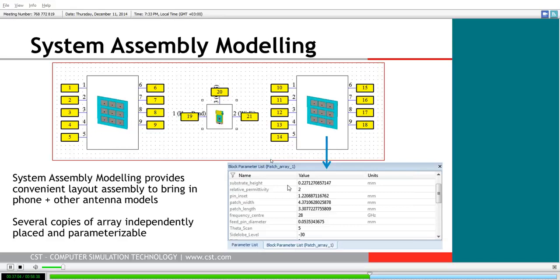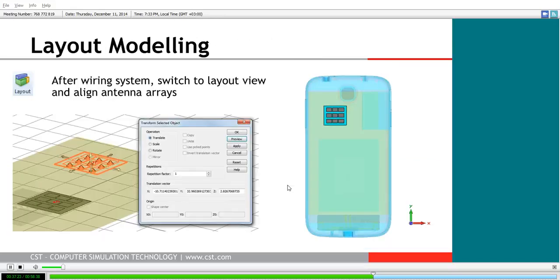Now, because we're going to be aligning these things, we're basically mounting them structurally. There's no electrical connection beyond those we'll form with 3D placement. All we need to do is just wire in external Design Studio ports to each of the wire terminals on these Microwave Studio blocks to make the system complete.